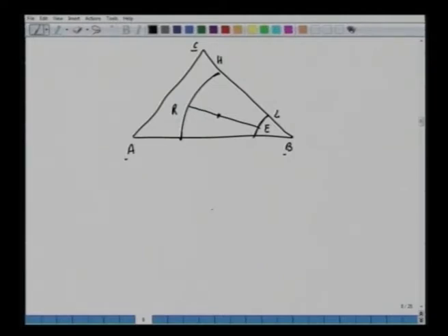Alright, so again if you choose M, mark this coordinate as M and say that you have reached the equilibrium, the raffinate will contain a certain mole fraction, say XR of C. The extract will contain a certain weight fraction of C again here. If you choose any other mole fractions here, again allow them to settle, there will be a tie line, and they need not be parallel. Again you can apply the mixing rule to obtain how much is the amount of R and how much is the amount of extract here.